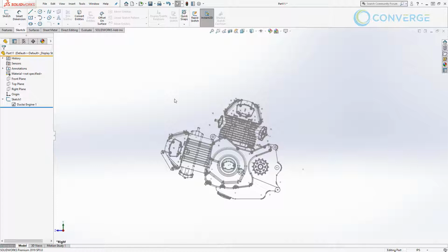One word of caution for you is make sure that everything is measured and scaled appropriately. We took the file in and it was scaled 1:1. We created a block and we brought it back. But it is important to make sure that when you get it back as a block that you scale it appropriately if you need to. So measure something off of the original, the diameter of a hole, the distance between 2 points, whatever you need to do to make sure that you have that scale right.